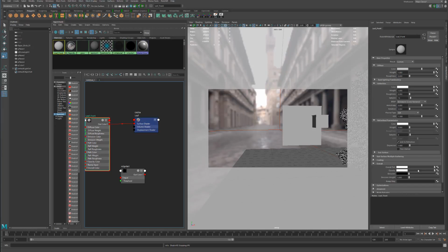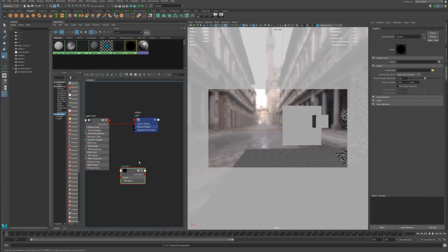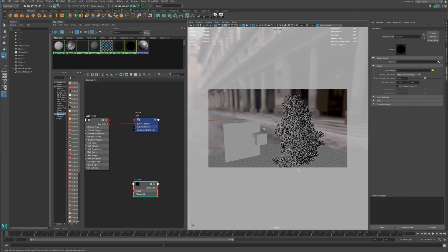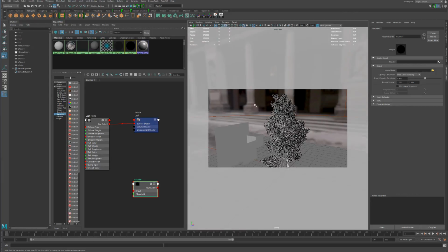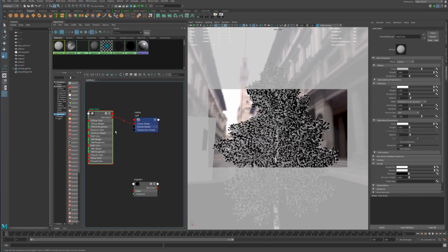I know some people notice that if you go under the Redshift material, under overall, there's the opacity slot. You can use gradiated cutouts in the opacity slot, but due to trace depths, you can only hit 16. The Sprite Shader negates the trace depths, so you can have basically as many as you want. This is really important for trees that have layered leaves. You have tons of leaves, and eventually if you just use the opacity, you'll start losing the details inside of it. The rays will cut off. Using the Sprite Shader negates this.